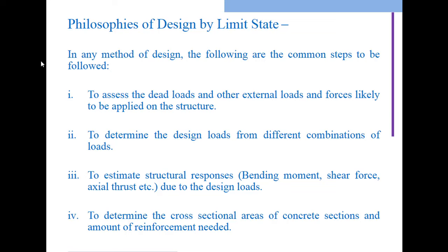Because if you constructed a home in 2001 and you construct two more stories on your existing structure in 2009, it means you are applying load again and again on the existing structure. That's why we apply a factor. Our factor is 1.5. If your current load is 10, you multiply it by 1.5, so your load will be 15, and you design accordingly for 15 kilonewton.